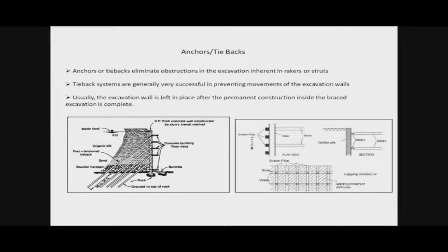In this tutorial, we are going to talk about the anchors and the tiebacks. Also, we are going to talk about the struts. So here you can see in this retaining wall, we have provided some tiebacks which go all the way into the ground so that it provides support to the wall. And the way it provides the support, it prevents the soil from collapsing.